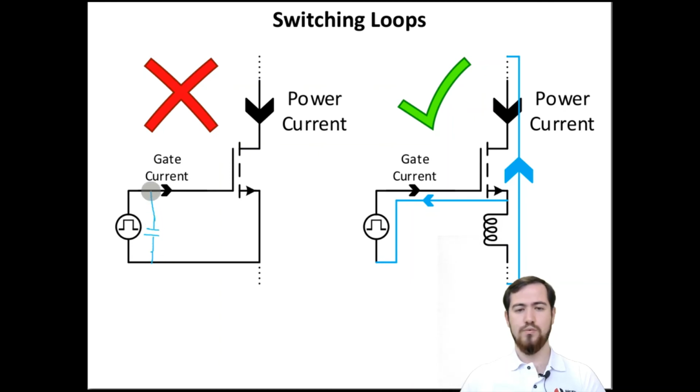So we need to connect this capacitance to the gate and the source pins such that it doesn't couple with a large amount of flux while the current is returning back to the capacitor. For that purpose, we need to put the return current path just under the incoming gate current path on the top layer or the other layers.